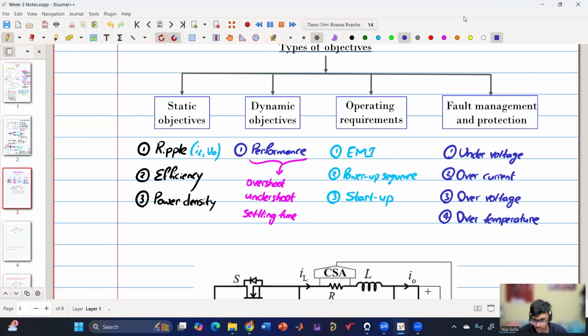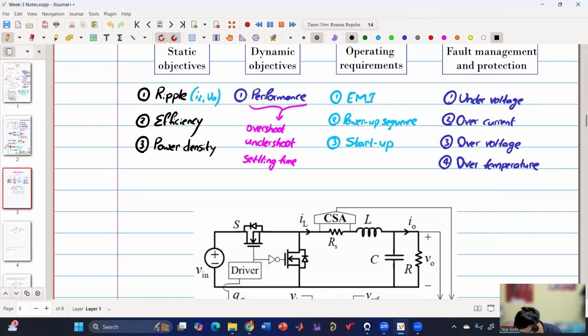So if I'm considering this as the battery, the old phone battery, there used to be gold color pins, one, two, three, which used to get in contact. These consist of three terminals: one is the plus VDD, one is the ground, which is minus, and one is for temperature.